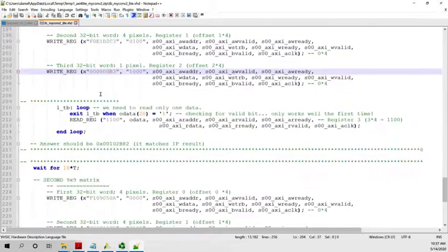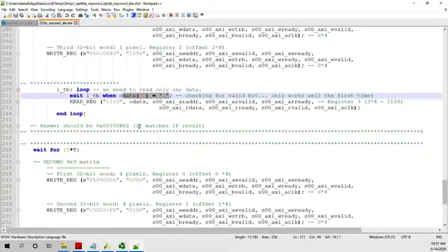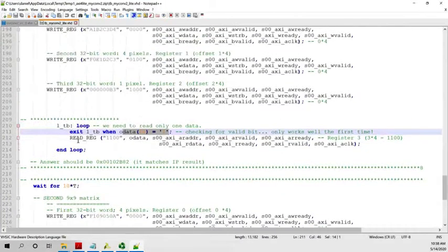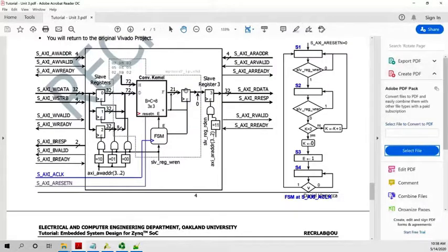And then, of course, you do a loop, and you have to wait for what? What is this? You remember? O data should be, if I am not mistaken, the following. We read a register, in this case register 3, right? And bit number 20, which is the V, because I happen to put that V on 20, although I could have put it anywhere in the 32 bits, but I prefer to put it as the MSB. So I have to check this.